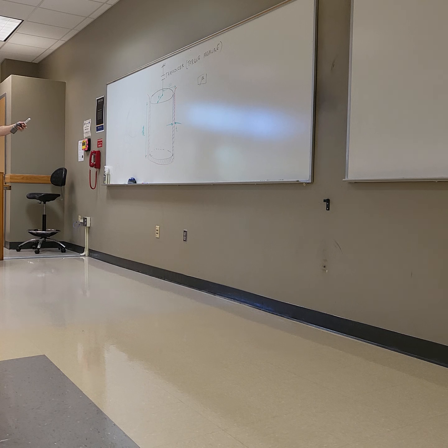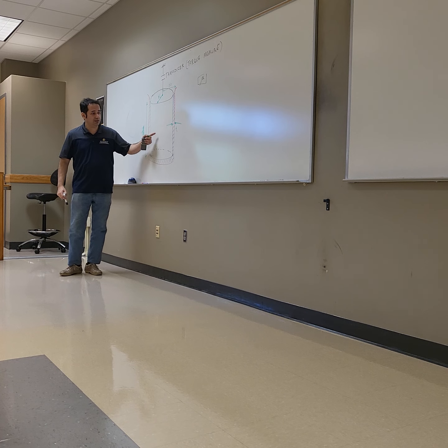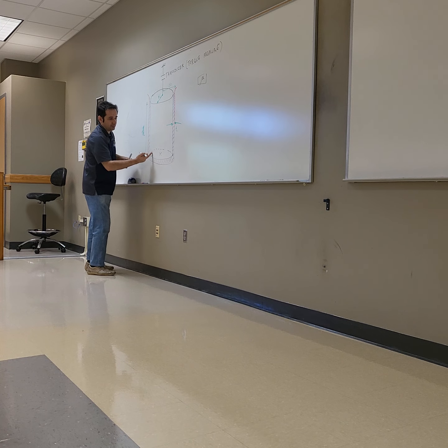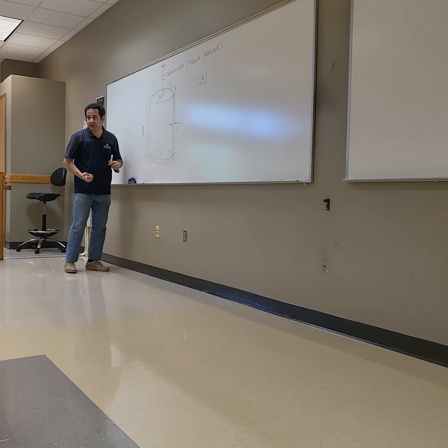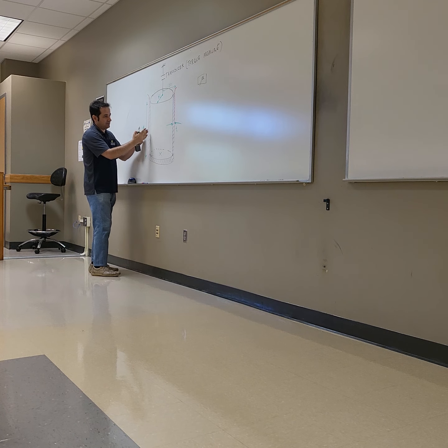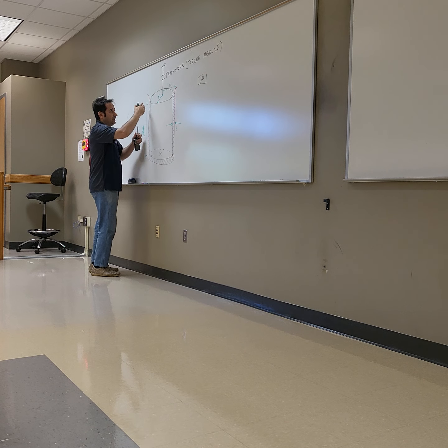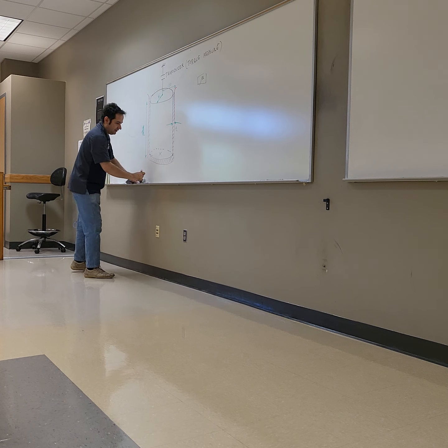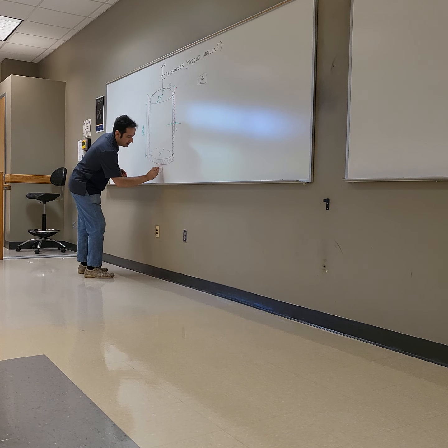But this method is in fact very accurate. In fact, if you go to one of our labs downstairs, they use precisely the same thing to measure the viscosity, right? Now, we developed a relation for that in the last class, but look, we ignored the bottom, right? So we only considered the fluid between the cylinder and the outer cylinder, which is rotating with a constant velocity, omega.